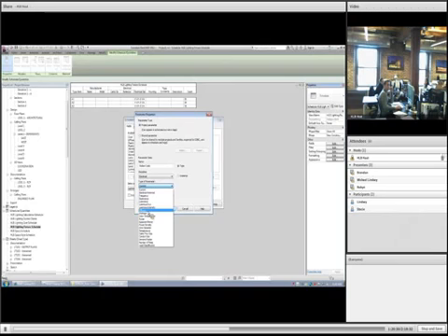For instance, it can't make the conversion from area to volume at all. Even if you know the area times a certain height, it can't do that calculation in a schedule, so it's particularly frustrating there. If you're trying to study your lighting from a volumetric standpoint relative to area, you actually wouldn't be able to make that conversion back and forth. So that's the reason that the type of parameter is particularly important, and really the discipline.